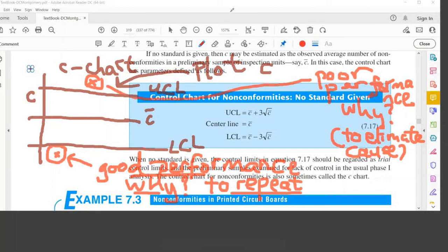But when we use the X bar chart, any point beyond the upper control limit or lower control limit shows the potential of having an assignable cause. When we use the X bar chart, which is a variable control chart, whenever an observation point is outside the control limits, above the upper or below the lower, it suggests that the process is having a problem.